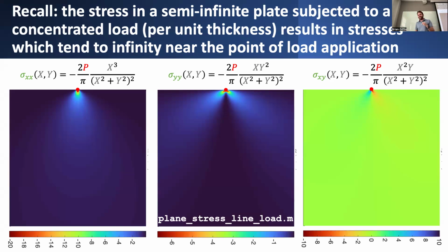And I'll reflect on the different aspects of the theory of elasticity. We should break it down and make sure that each of the different components that we've put together, these three primary constituents, compatibility, constitutive law, and equilibrium, we examine each of those and really say, was there a false assumption that we made somewhere along that line of putting all these different relationships together? Was there a false assumption we made that makes this seem rather unphysical? So let's go down the list.